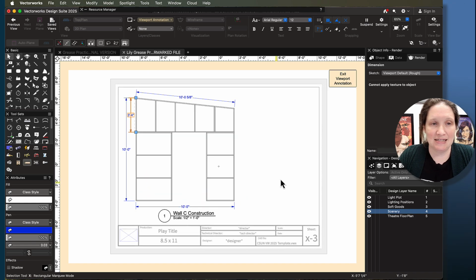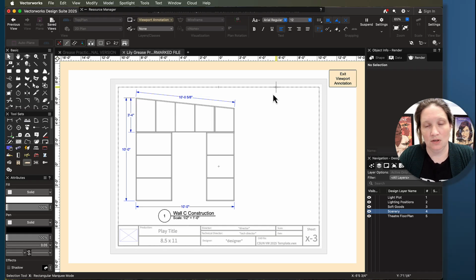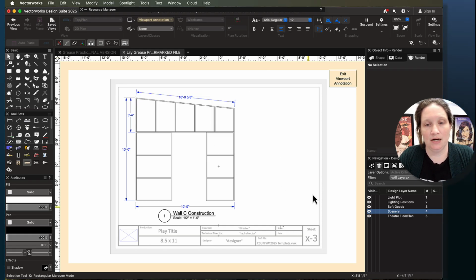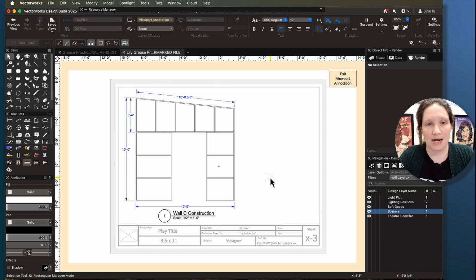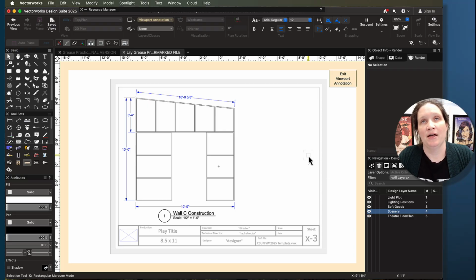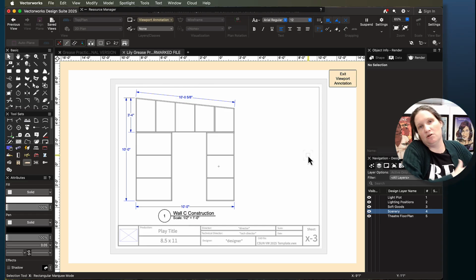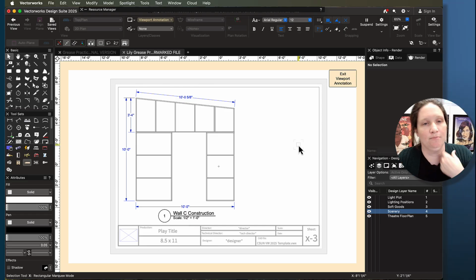The next step that I would like you to do as part of your project here is to place a cut list next to this annotation, right, on the drawing. And I'm going to have you put it inside the viewport. You could put it outside the viewport on the piece of paper. That would also be fine. But I'm going to have you put it inside the viewport. And the reason is that if I were making like a big sheet of drafting, I could then pick up the whole viewport and all of those notes would come with it automatically. Okay.